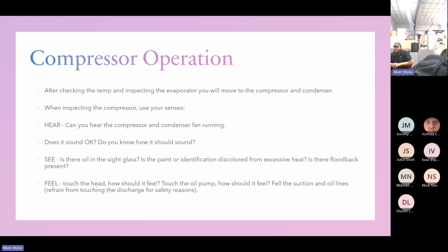Touch the head of the compressor. How should it feel? Is it really, really hot? Is it cold? Touch the oil pump, if you have an oil pump on it, like a supermarket or rack compressor.